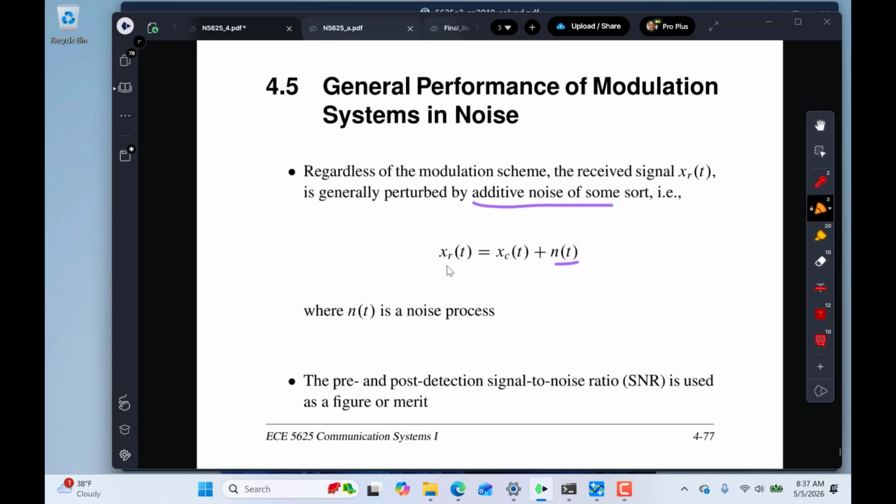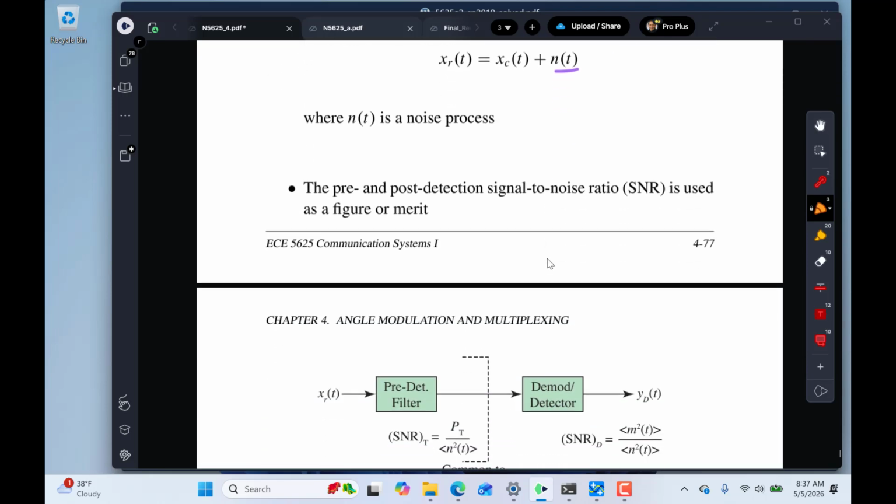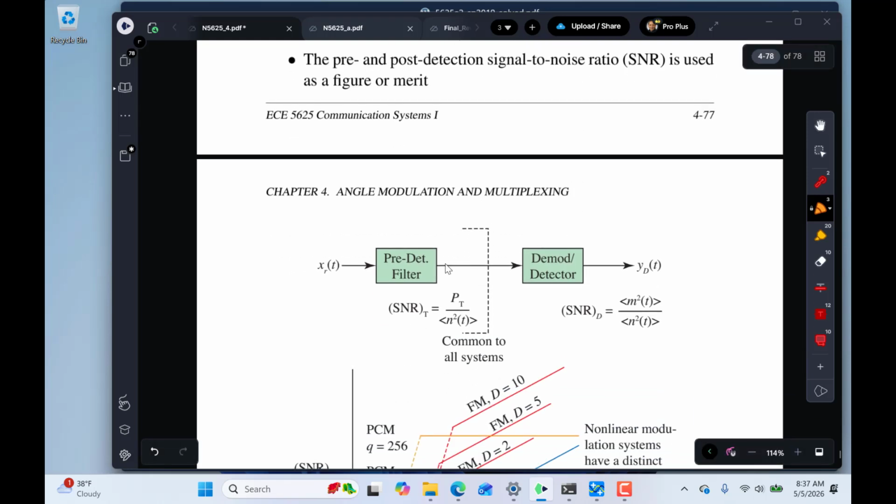He says, okay, a received signal is going to usually be accompanied by some receiver noise, and we're going to have to contend with that noise. So in simple terms, how does this receiver work when there's noise present in addition to the signal? We're going to have some measure after our bandpass filter or something to just eliminate adjacent channel signals and so on. We'll have noise getting through this filter, subject to Appendix A actually, and we'll have signal power, PT, that'll be the total received power from the transmitter at the receiver, and that forms a ratio.